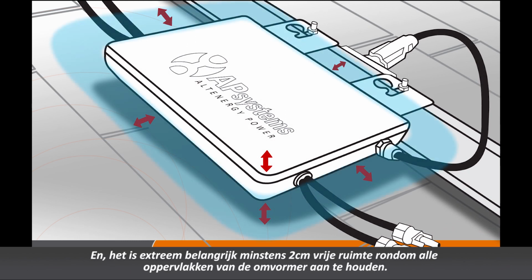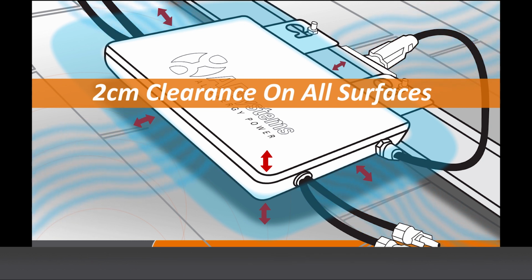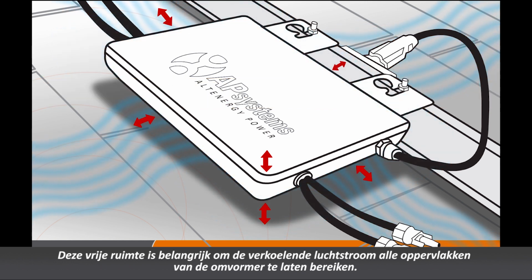And it is extremely important to allow at least 2 centimeters from all surfaces of the inverter. This spacing is important for cooling airflow to reach all surfaces of the inverter.